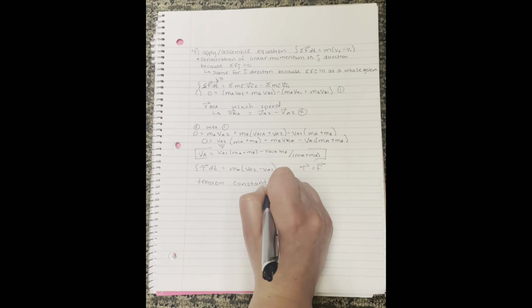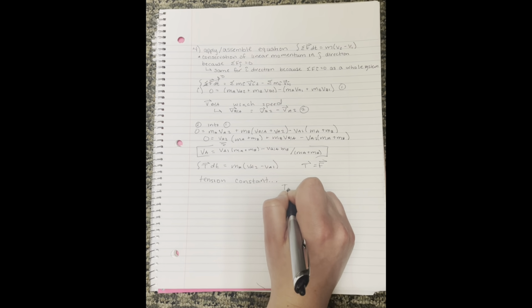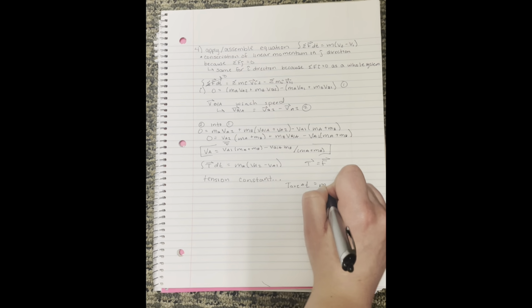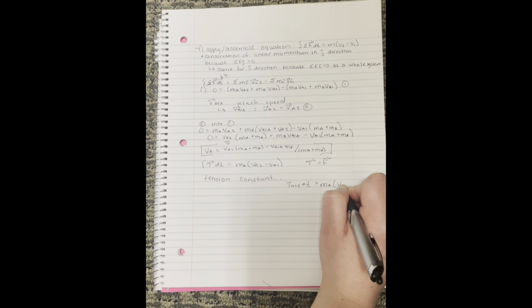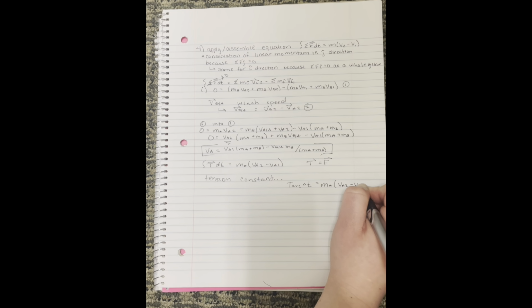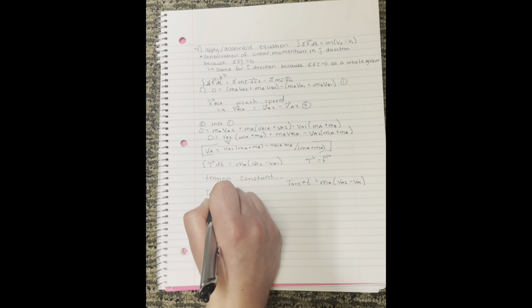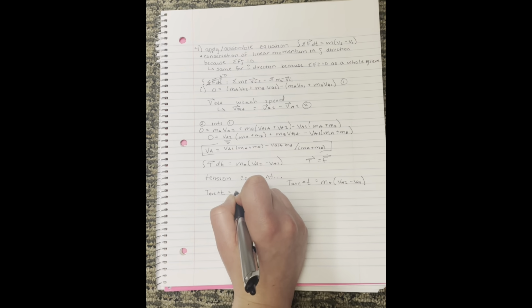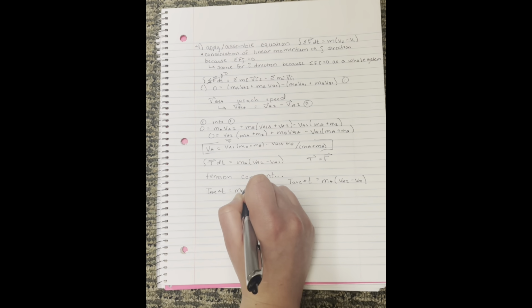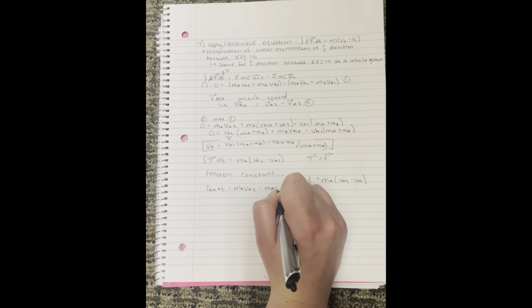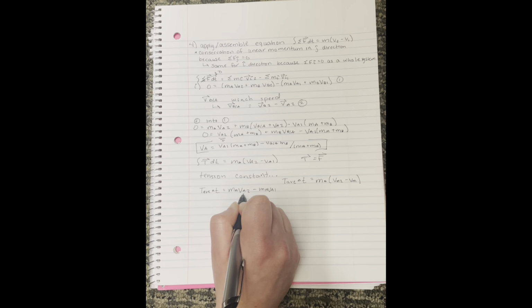So we're going to end up using the equation T average times the change in time equals mass A times the two velocities subtracted from each other for position 1 and 2. This simplifies down to T average times delta T is mass A times the second velocity minus mass A times the first velocity. And this second velocity for A is what we find up here.